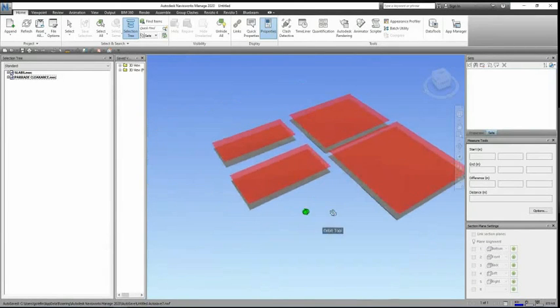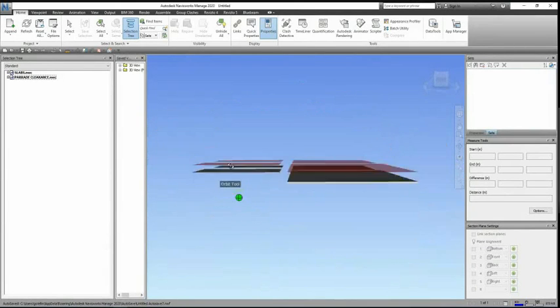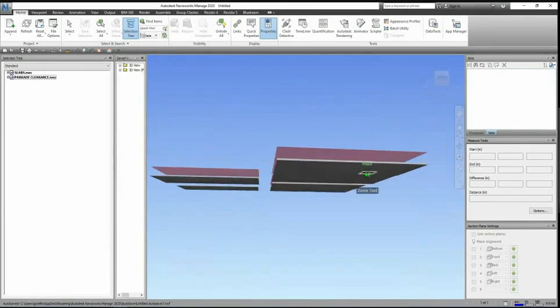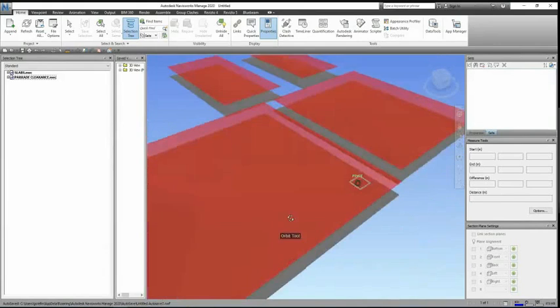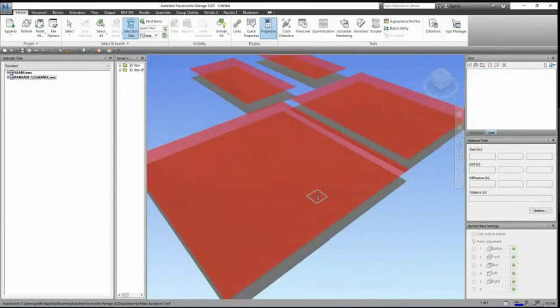So yeah, that's basically how to create floor slabs with a slope, and also for multiple slopes, and create a parkade clearance that will reflect the same contours of that slab.